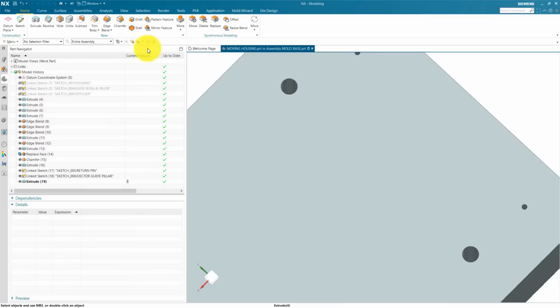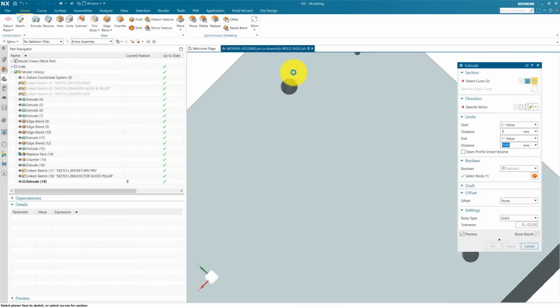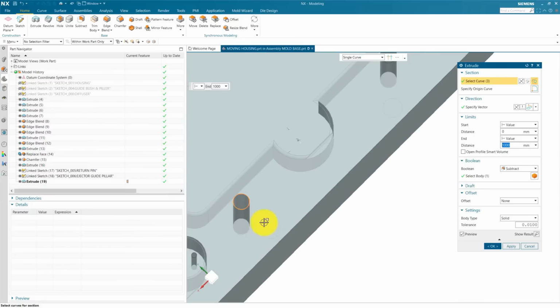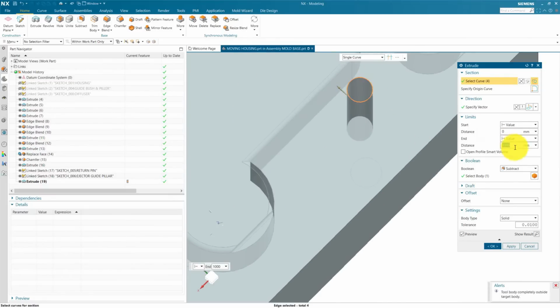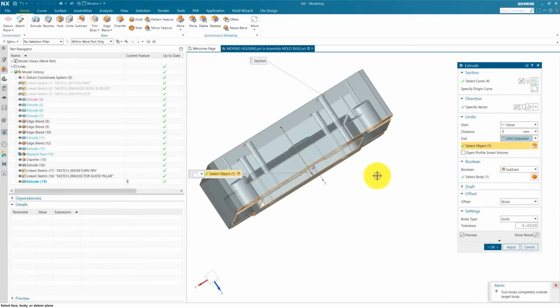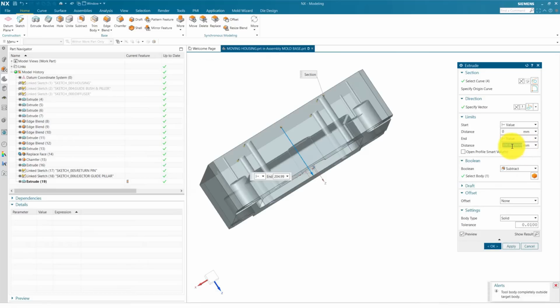Now we are going to add some relief for our return pin. So for this, select this bottom edge and select all 4, and we are going to use until extent and select this face and change this to value 205 approx. 205 minus we use 60.